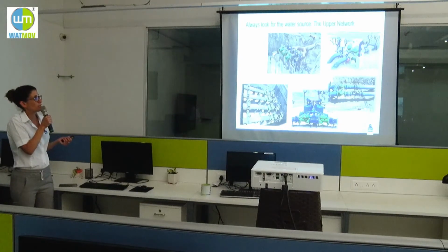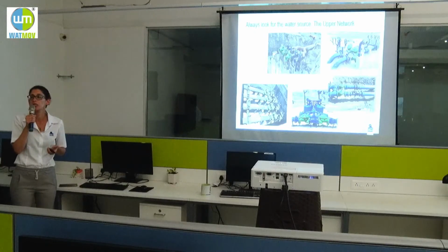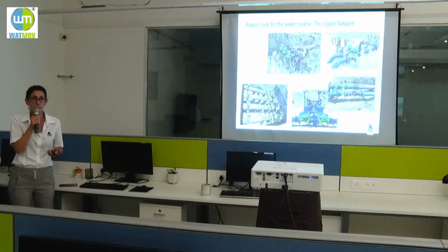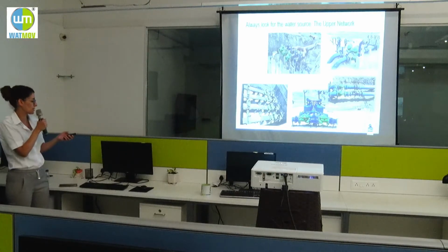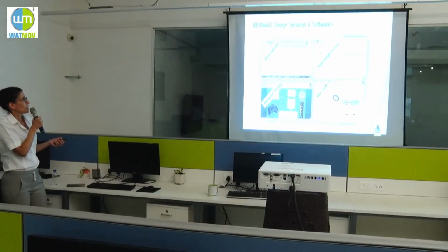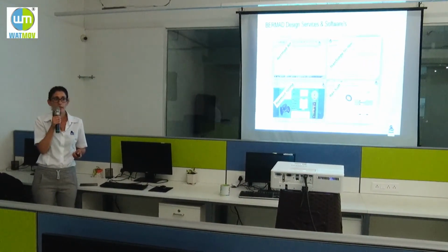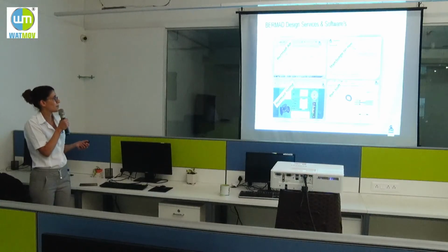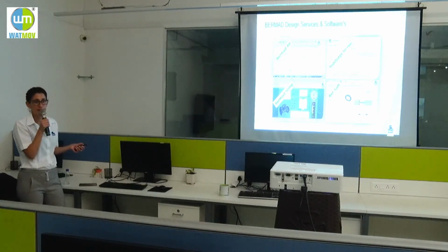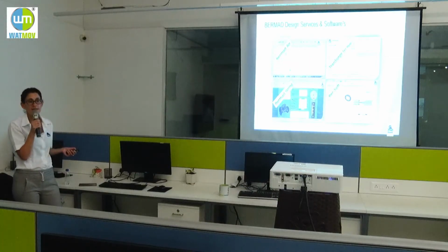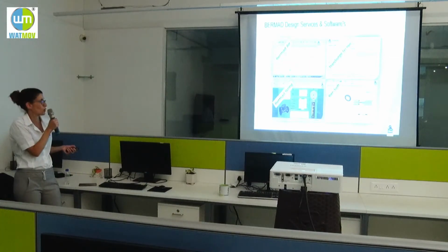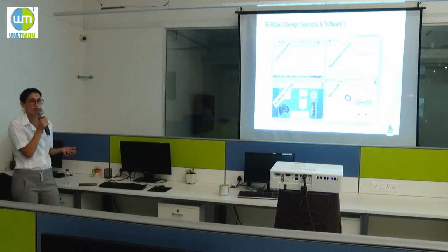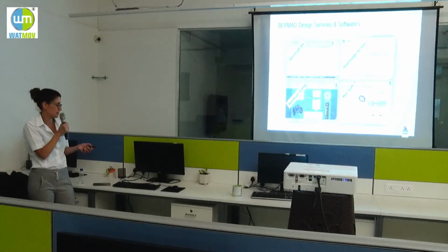And here we see pressure reducing valve in a very big project in Peru. It's a center pivot, if you know center pivots, irrigation machines, a project that we supply. And this is all Bermad tools that I talked about: Bermad air valve, allocating and sizing, Bermad sizing for optimizing the hydraulic control valves for the conditions in the system, Bearsoft, here you can see a design of an orifice for flow control, and surge solution analysis.